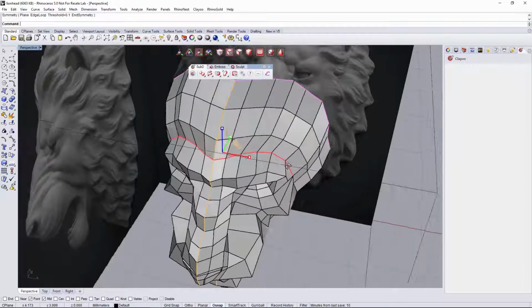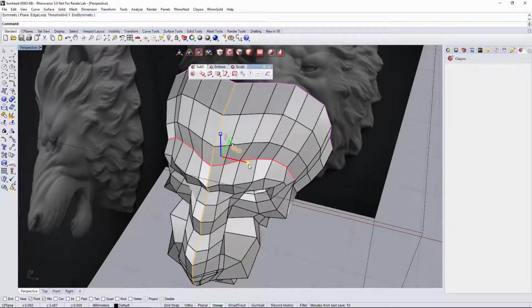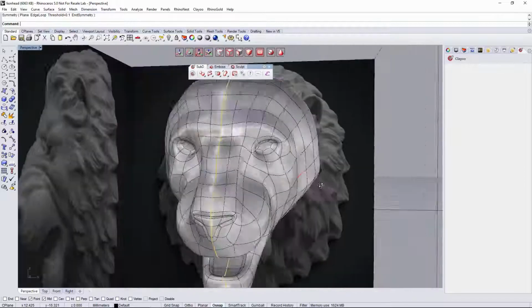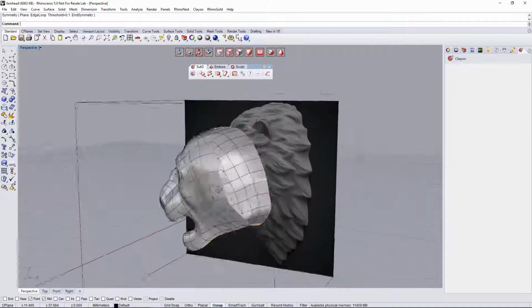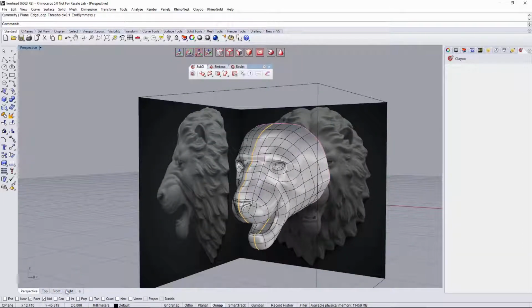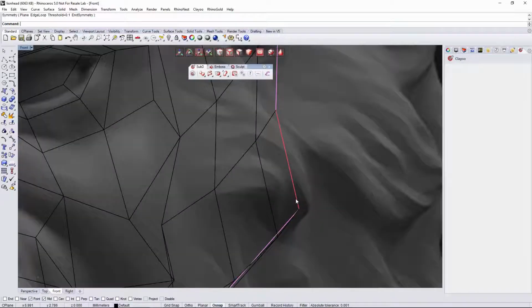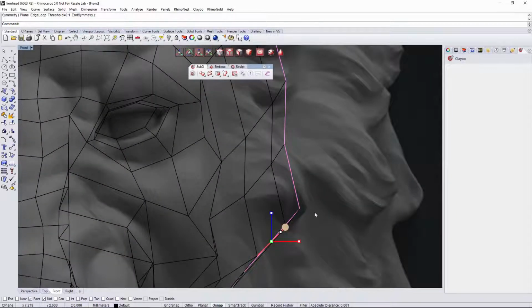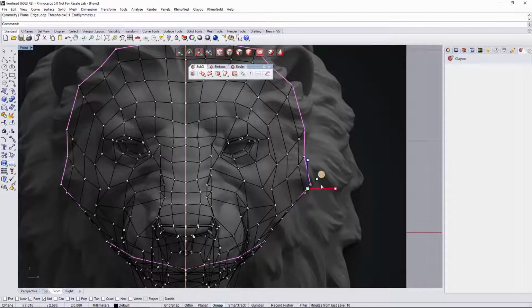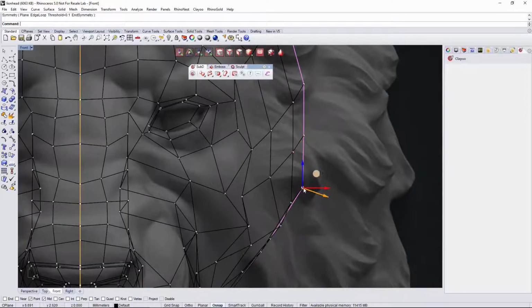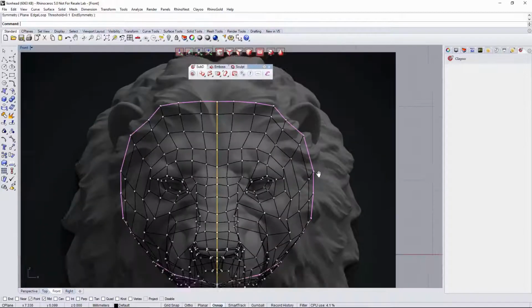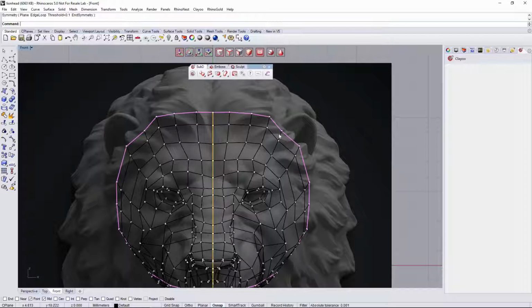Maybe a real lion has this part a little bit more straight. Maybe from the front view now it's too stretched, but no problem. Anytime we can just refine all the shapes in here now that we have symmetry active. So the changes on one side will be applied on the other one. So it's gonna be much easier to change anything.